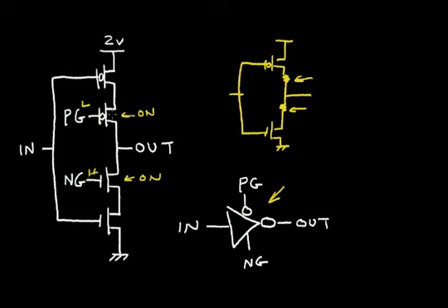However, again, if this PMOS transistor here is off and the NMOS is off, these resistors are open circuit, and the output is detached from the circuit. So the output just floats there, or we call it the high Z state. It's completely disconnected from the circuit function. So let's consider what we can do with this tri-state driver.